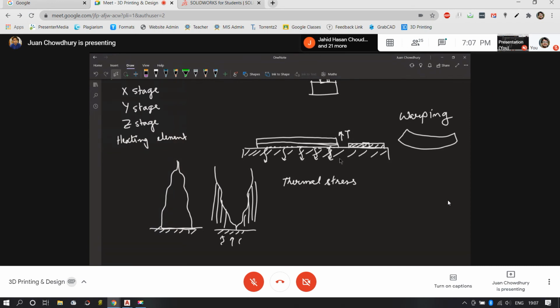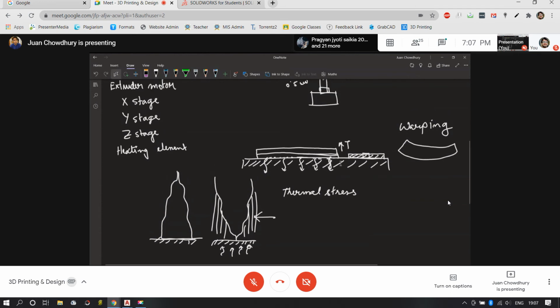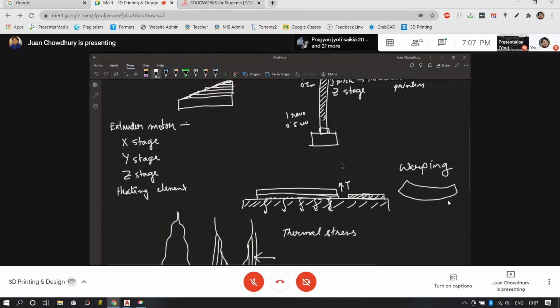Heated bed. Okay. So if you're buying a DIY printer for yourself, which is of course a fun activity, this costs around 15-20,000, make sure you have a heated bed. Otherwise, you'll end up spending a lot on these supports, which are useless and will of course damage the surface texture.